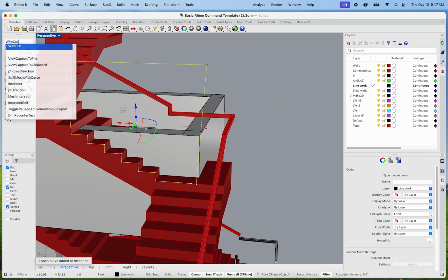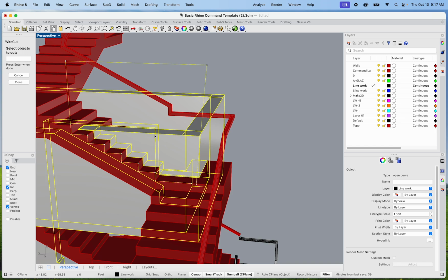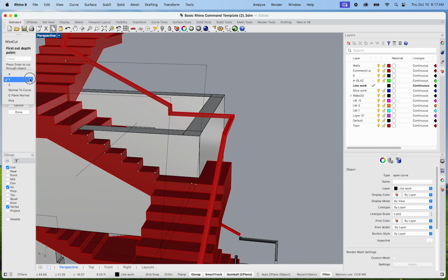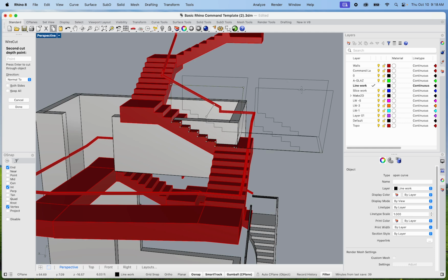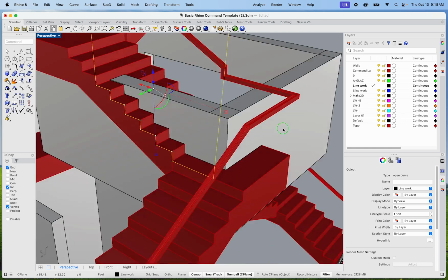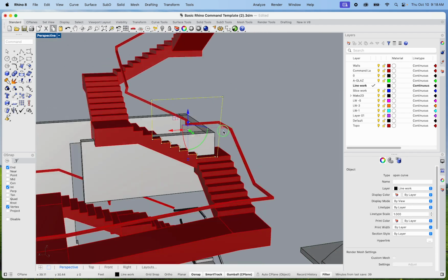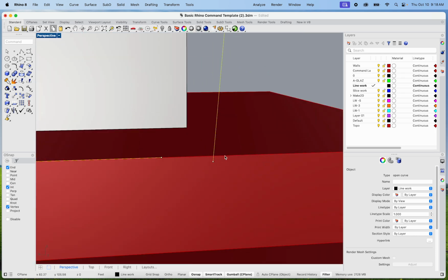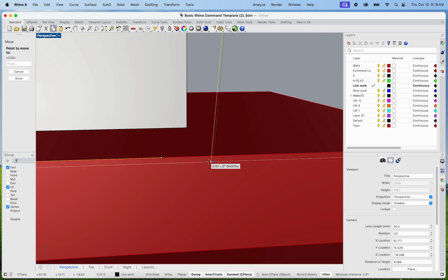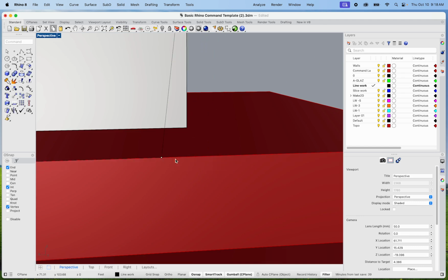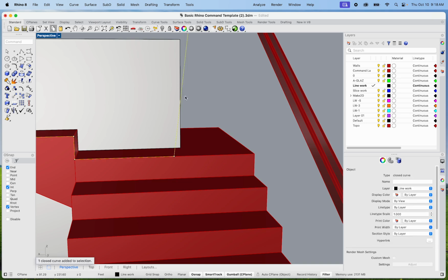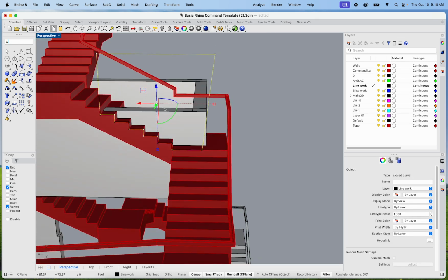Wire cut. Perhaps a different direction. Sweet. X direction. Well, it does technically need to go that way and that way. It doesn't seem to be cutting anything. Why not? Do I have a closed object? I'm pretty sure. Oh, that'll do it. So I don't have a closed object. Forgot to close the rest of my curve afterwards. But that's okay. Now we got a closed curve. Let's try that again. Wire cut.